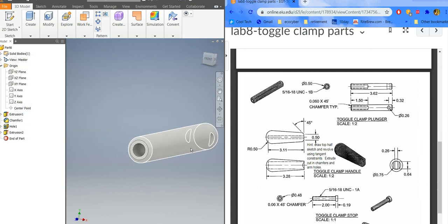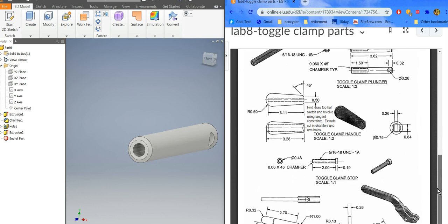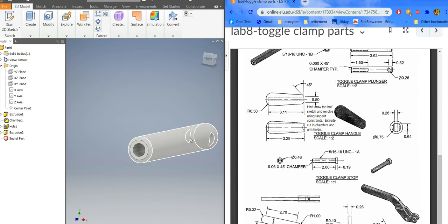Okay, when you dimension this one, it's going to be hard to dimension because it's like an ellipse when it cuts through there. So to dimension it, you need to share dimensions when you're into dimensioning, and that'll let you dimension that on your drawing. Or you can do a section view of it, and then it'll be round. You can dimension on the section view. Okay, so that's that one.